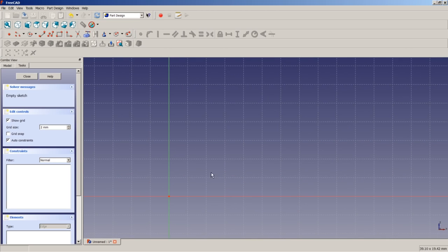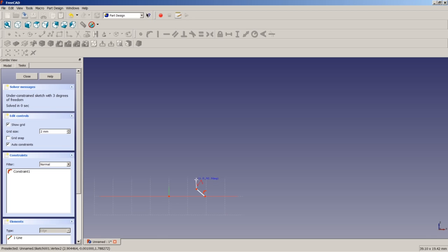So now we will draw once again our revolve profile with the polyline tool. We will begin on the horizontal axis, doing a slope here, going vertical a little bit here, do one zigzag, being once more vertical here, doing a second zigzag, being vertical here, doing once more a zigzag,